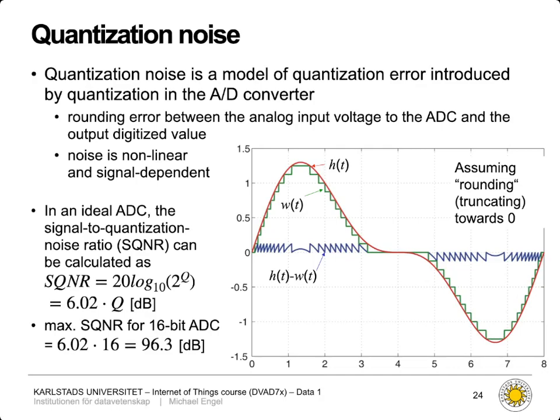And you might have heard this noise if you used MP3s many years ago to save space on your precious SD cards, which were very small back then. You tried to sample signals not only with a low sampling rate, but also with a low number of bits. For example, if you sample audio signals with only 8 bits, this is not really enough to reproduce music with high fidelity.